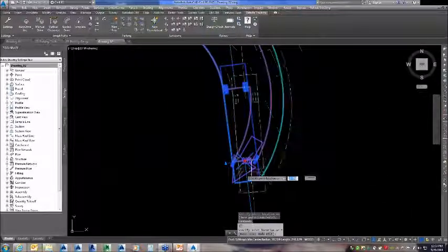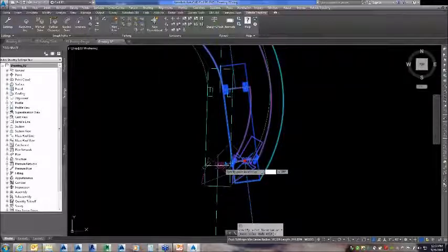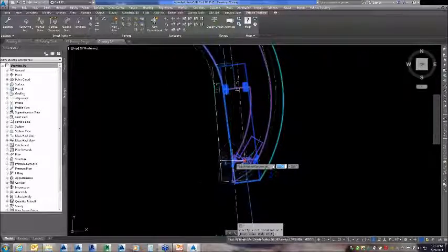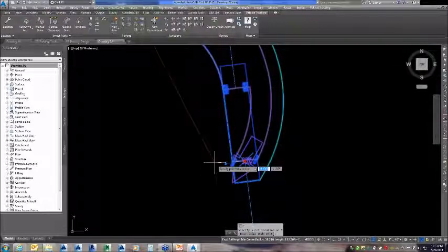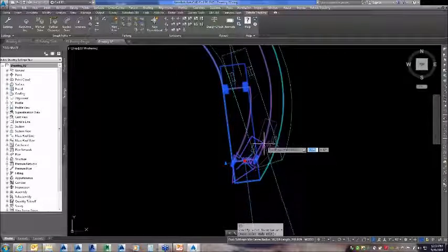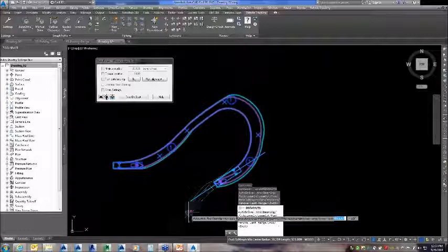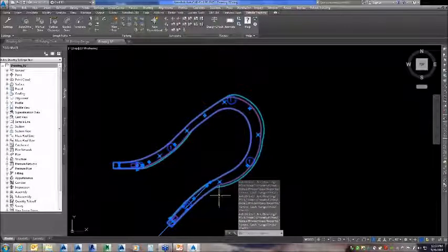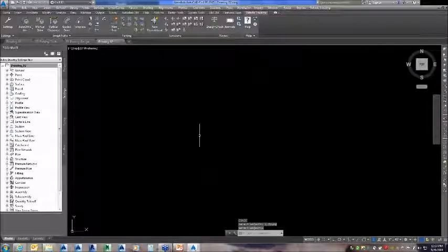If it doesn't make the steering based upon the standards, it puts the red line in there. So as soon as I get back, it shows me my path that I can drive through. As soon as I go outside of it, it lets me know that that will not work in reference to that vehicle. Okay? So again, just kind of giving you a basis. And if I wanted to, I pick on it, and I just say AutoDrive again, and I can continue from that point if I wanted to. Okay? So pretty straightforward. And if I didn't want this, it's just an AutoCAD object.